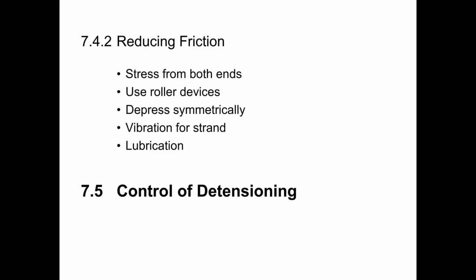So detensioning is basically the same as straight strand, but with a little more complication in that we don't just need to make sure that the strands are detensioned simultaneously and symmetrically, but in addition, we need to make sure that we're detensioning bottom strands at the correct time versus drape strands, and that we're releasing the hold down devices at the right time as well.